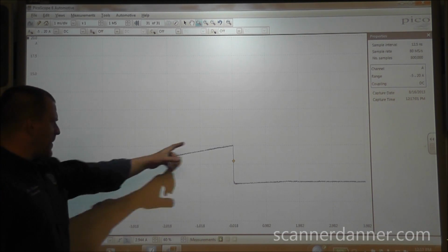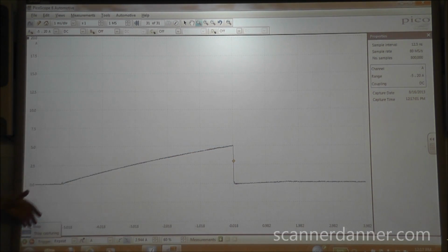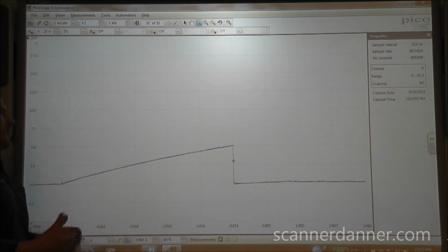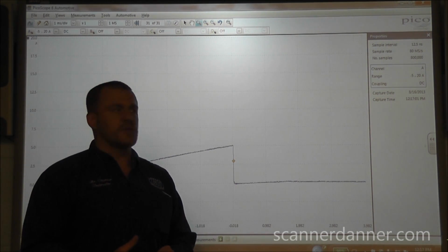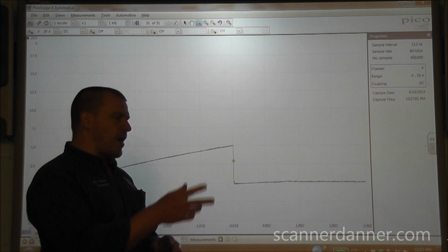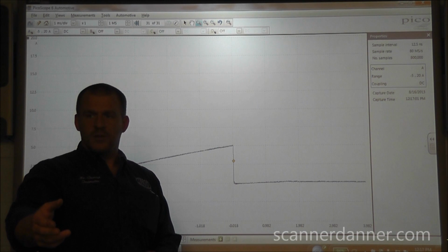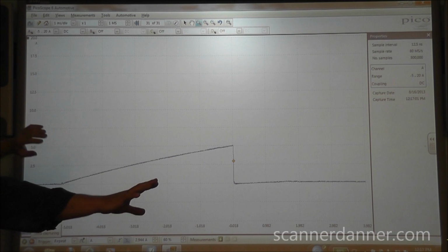You guys can see here that this pattern has really a maximum of about 5 amps of current. And remember, this is a voltage conversion here. It's an amperage scale. It's not really amperage, but we have a 5 amp reading here. Let's say I want to look at a fuel injector. A fuel injector on this Jeep probably draws about 1 amp of current. So I take my amp probe off of my coil, and then I reinstall it on my injector, and I don't change any other setting. I would maybe still use the same amperage scale. We're not going to do that.